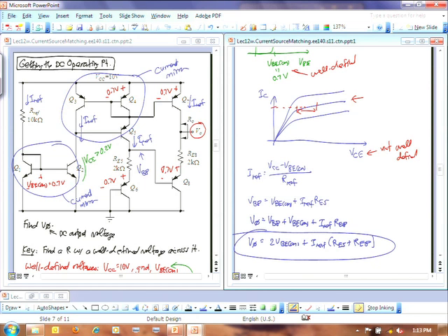Okay? So it looks like a pretty big circuit. But if you can recognize parts of things in this circuit, right? If you can recognize that that's a current mirror, that's a current mirror, this is a current source that's being created by the V bias. This is basically a V bias that was generated right here by that current mirror. It's giving that V bias to this transistor and to that transistor. And if these transistors are all sized the same, which they are, then you have IREF going through all of these things, and I can easily determine what that output voltage is.